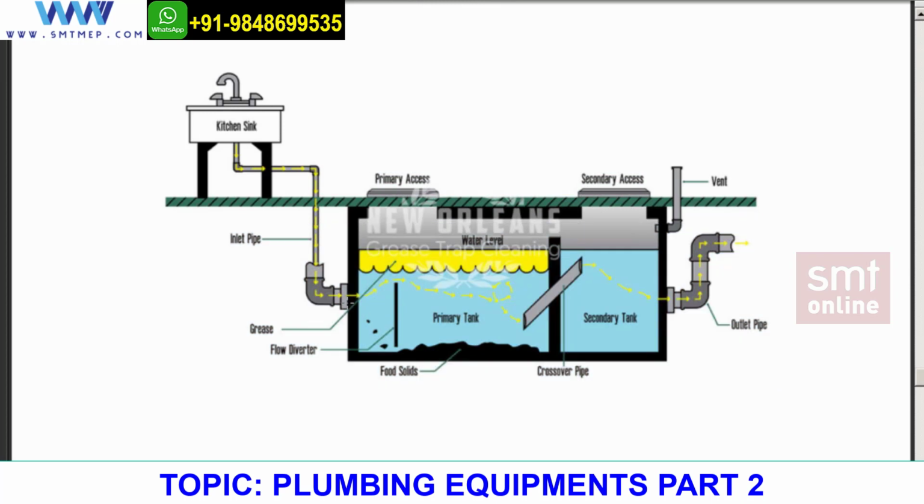Some solid particles will hit this and try to settle down. Now when it is there, the water goes in this way. This is being filled and the water can pass from here also because you have a little space here. Now the water goes in this way and the solid particles, the food solids, you can see have settled down. From here to here it takes time, and to fill this up it takes time. And don't worry, as the new water comes, it replaces the old water. So old water continuously drains out because the new water is entering.